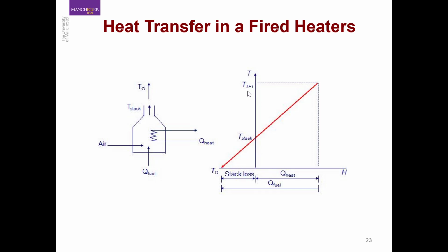What is happening inside this furnace is graphically represented here. You start with the theoretical flame temperature. That will be the topic of our next video, and it is essentially the supply temperature of the flue gas. Then you use this flue gas to heat up your process fluid, and as such the temperature of the flue gas decreases. Based on the shape of the GCC, your pinch point and dew point, we can determine what our stack temperature is.